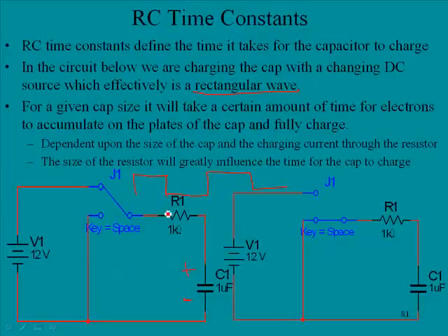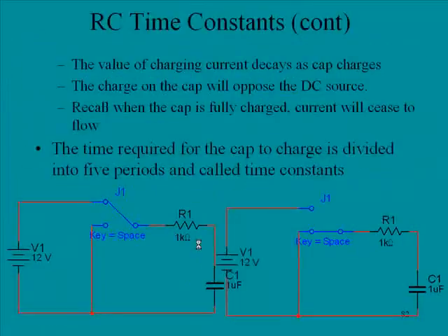Again, depending on how long the voltage is applied and how much current flows will affect how long it takes for this capacitor to actually charge. The size of the resistor will greatly influence the time for the cap to charge. So the size of this resistor has a great deal to do with how long it will take this capacitor to charge. Now, let's continue with this discussion.